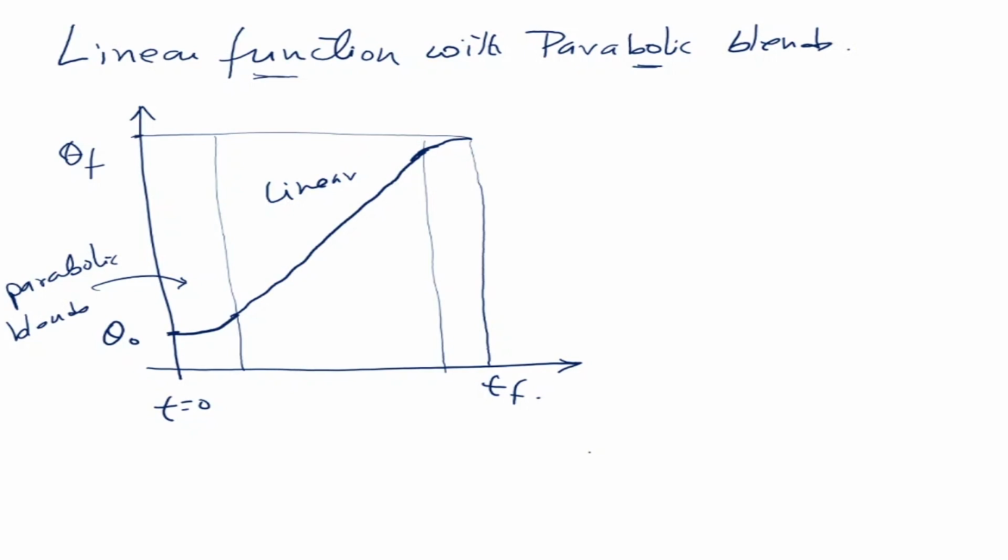Now, something to note here is that the time of the parabolic blend is TB. Okay, and exactly on the center portion, this is TH, T halfway. It is symmetric about the halfway mark. Now, in terms of the thetas, this is theta H, the halfway mark, and this is theta B, which is the distance it has moved in the blend section.